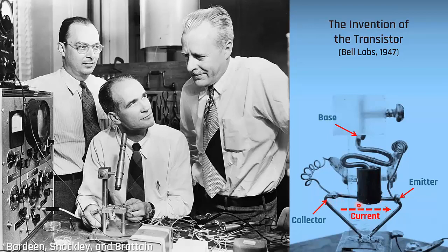If it's on or off, it becomes a digital switch. If it's a bit stronger or a bit weaker, it's an analog amplifier. The difference between this and a triode vacuum tube was that the triode vacuum tube worked by making a big electric field with lots of voltage, and adding something else to it would cause electrons to fly through a vacuum.